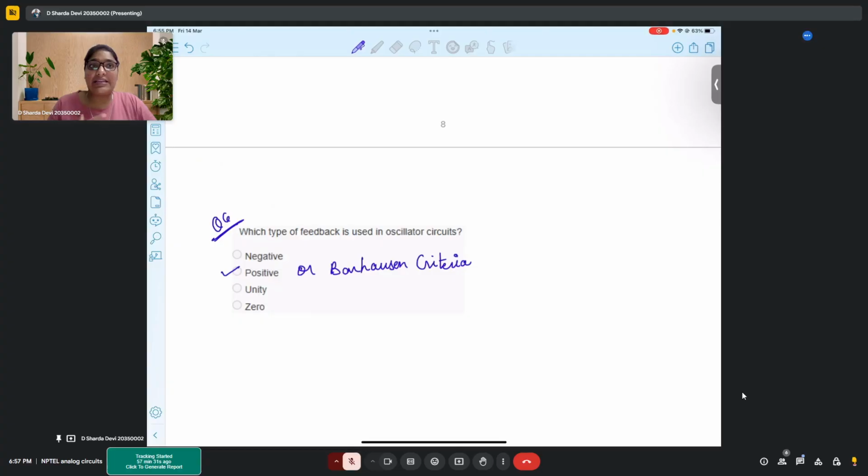So in general, it is asked, for designing an oscillator circuit, what are the requirements? Can negative feedback be used for designing an oscillator circuit? The answer is yes, and we will see the circuits. Otherwise, the moment you have a positive feedback, you can get the oscillations. The only concern is with positive feedback, the control is not that handy. So user control is not optimal in positive feedback. So that's why people thought of